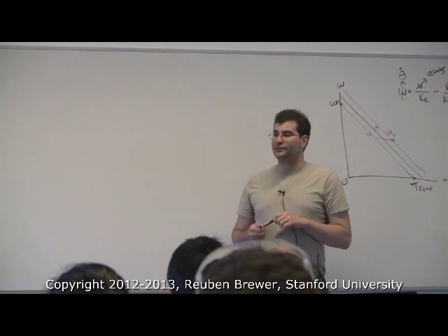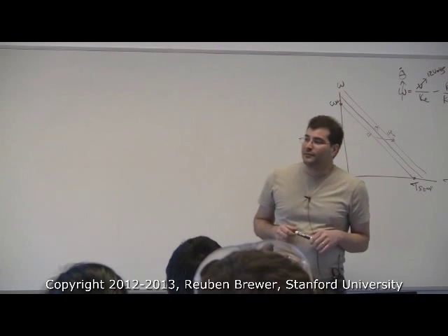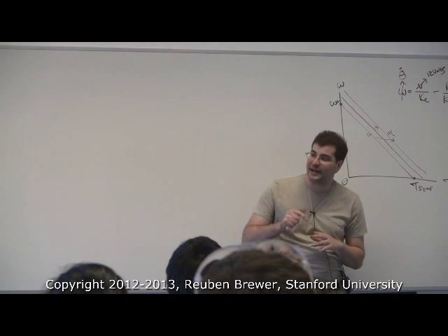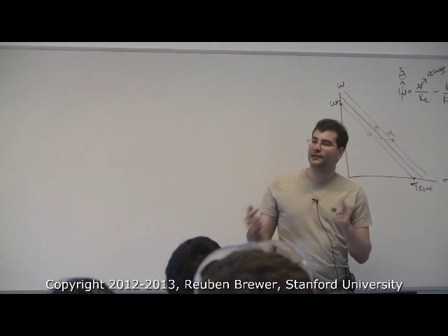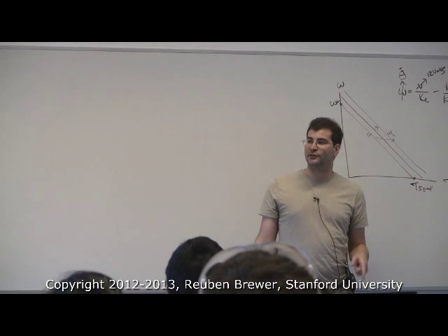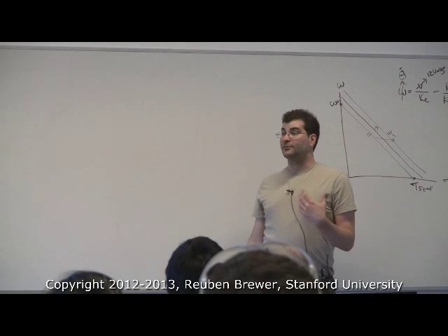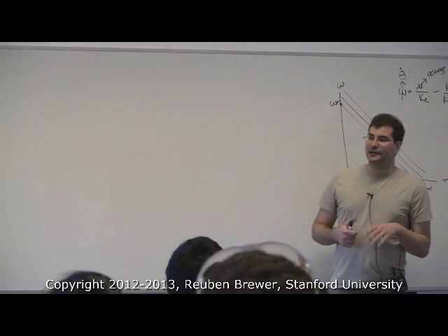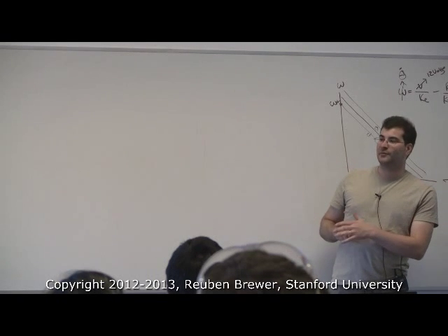If you are doing it yourself, you're going to be limited by basically the speed of the microprocessor's oscillator, and so you're going to be trying to go as fast as you can. You're going to be trying to beat 20 kilohertz, but you may not be able to, and if you do, it will be barely. So you're not going to be like, oh, I'm going to go up to 48, because your oscillator won't necessarily be able to do it anyway, depending on which micro you're using. So practically, you either buy it and you don't care about it, or you're just damned glad you got as fast as you could from the microprocessor.